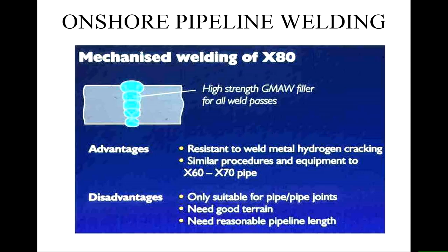So if you're just doing 5 or 6 lengths of pipe, a few hundred metres of pipe, that's probably going to be done all by sticks manually. If you're doing a 150 kilometre long pipeline, you're definitely going to be using the mechanised welding technologies.